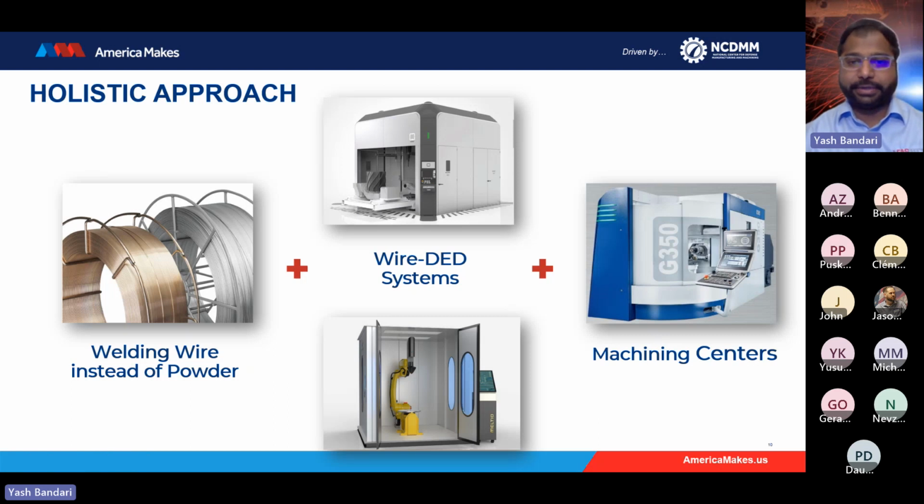It's no brainer that everybody knows that the parts that come out of wire-DED systems are a little rough, about 250 to 500 microns surface finish. So it's always required to do one final finish machine so as to get to the right tolerances required for the part to fly, for example.